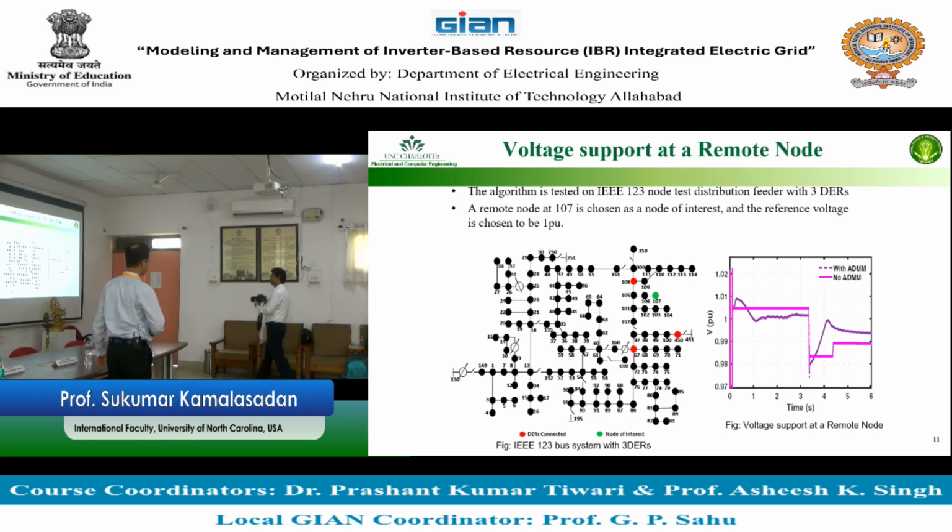How do you get an electric grid model? Well, if it is a steady state electric grid model, you can pick it from your power flow. Remember, we have a power flow model ready. So if this model is changing, you cannot pick it from the power flow. What you do is take the power flow models and find out what will be the impedance of the electric grid when the voltages and current change. Such an impedance representation, looking at the voltage and current, can be done through what we call Thevenin impedance.